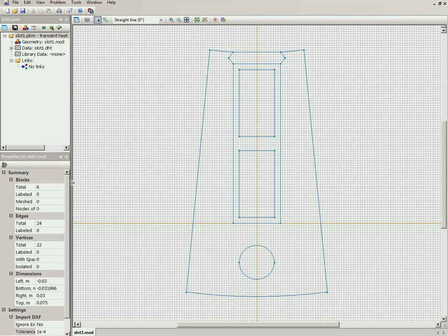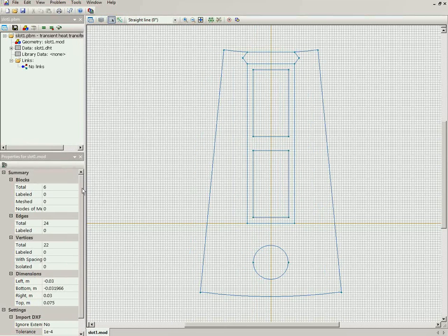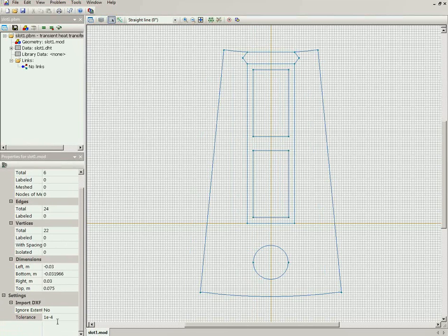In new version, it is possible to specify the tolerance. The tolerance means the ratio of large object to the small object. You see that if you have very small objects, for example, with the ratio of large to the small of about 10,000 to 1, the small objects may appear distorted or be missing.